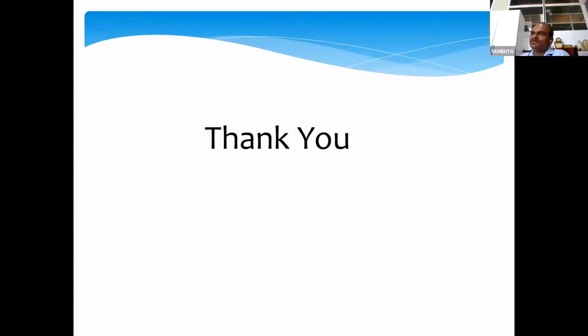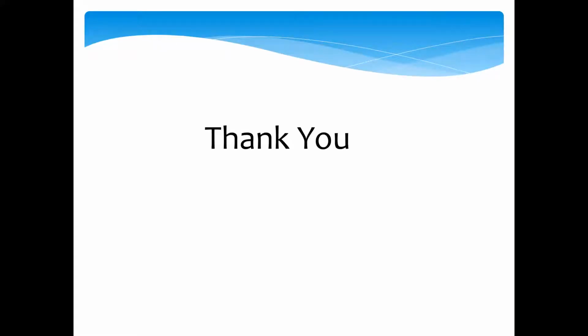Yeah, that is a very good question actually. Luckily, I don't know whether I was sincere or just too interested, but we were very cautious to operate that instrument so that it should not go bad, and we trained the students to be very careful. First of all, sudden rainfall generally occurs during the evening time, so we have to take care of that. We always have to be alert, because with a lidar, any small drop of water can cause the optical instrument to go bad. Yeah. So that is one caution.